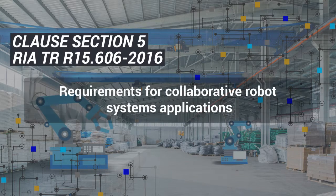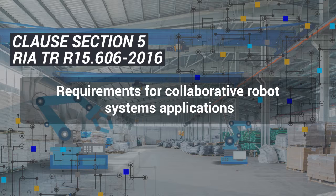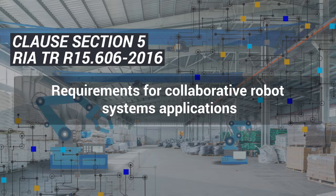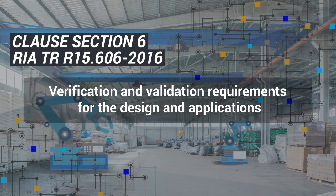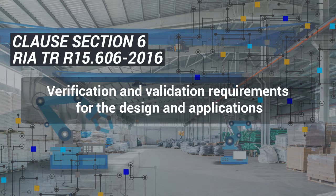Clause Section 5 prescribes requirements for collaborative robot system applications. The section covers the design and development of workspaces, robot operations, and lines of defense, for example, safety-rated monitored stop. It also includes speed and distance essentials and preventive hazards by continually assessing and mitigating risks. Clause 6 talks about verification and validation requirements for the design and applications.